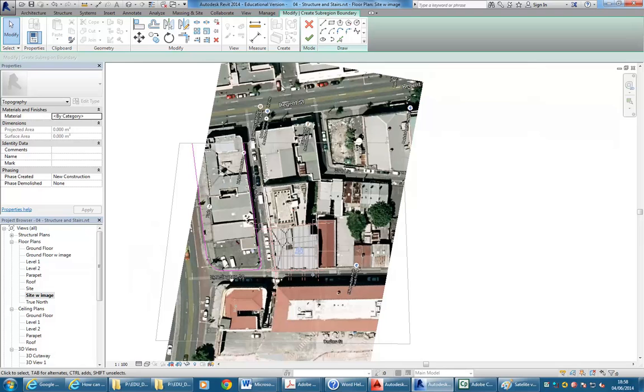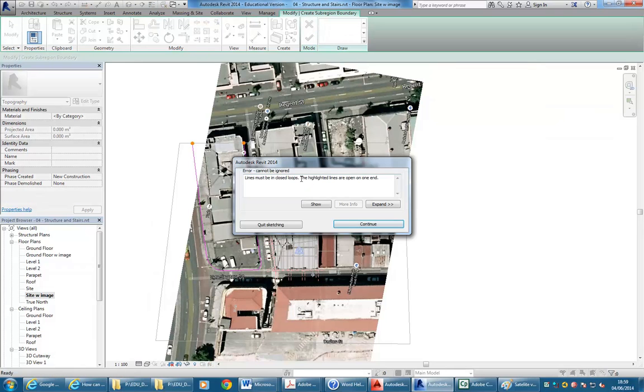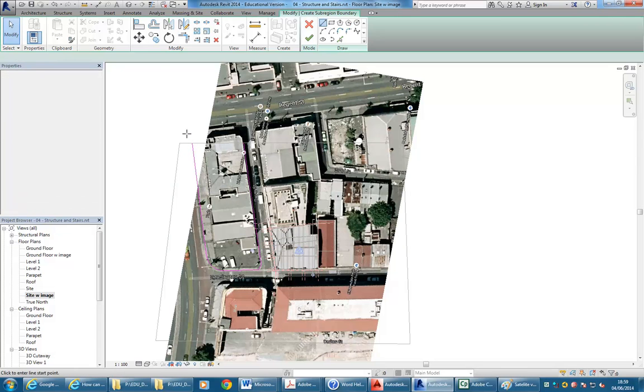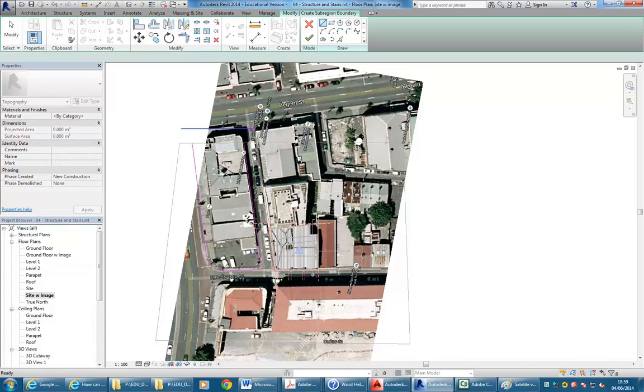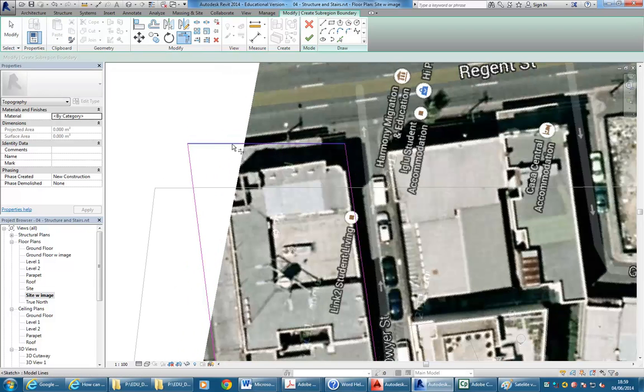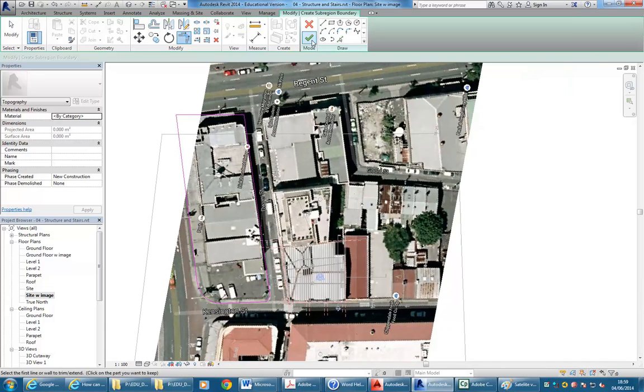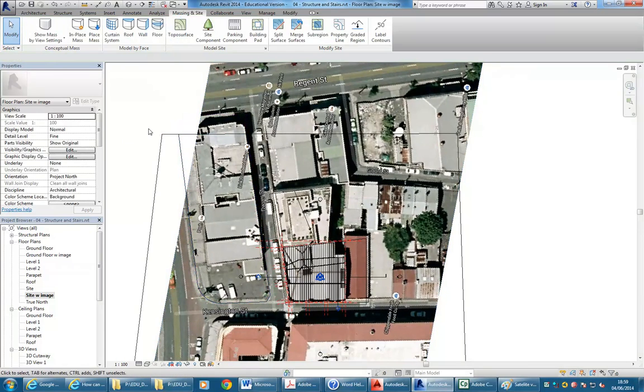Okay, so that's my new block shape, tick to finish. And now, sorry, I'm thinking of something else. So they do need to be closed, but again, don't go over the edge. It's better to bring it outside. So there are split surface where it's the other way. But this will work. So that's going outside my topo surface, which is here. That's fine. It should still, yep, it'll still work.